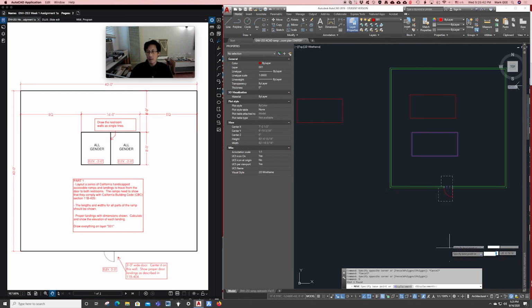I can click anywhere I want here, move the mouse, and it gives me a preview and shows me the vector direction that the motion is going in. Again, here we're in ortho. If I want to move it anywhere, I can hold down the shift key and override ortho and put it anywhere. Let's go ahead and do that. I'll hold down the shift key and put it right here, somewhere in space near that other box. You can see that I'm not moving it in a right angle, so that's fine. It's just out of the way.